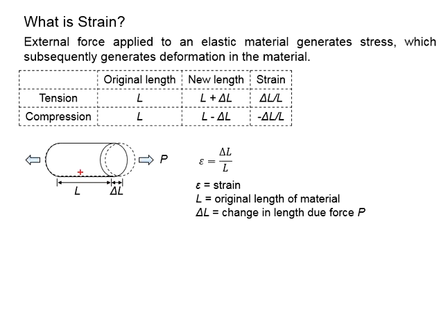First, when a material is subjected to external forces, for example this one, a pulling force P is applied to the material. The force here will generate stress over the cross sections of the material. The equation for the stress is this, which is the force applied to the material divided by the area of the material, assuming the force is equally distributed throughout the cross-sectional area.